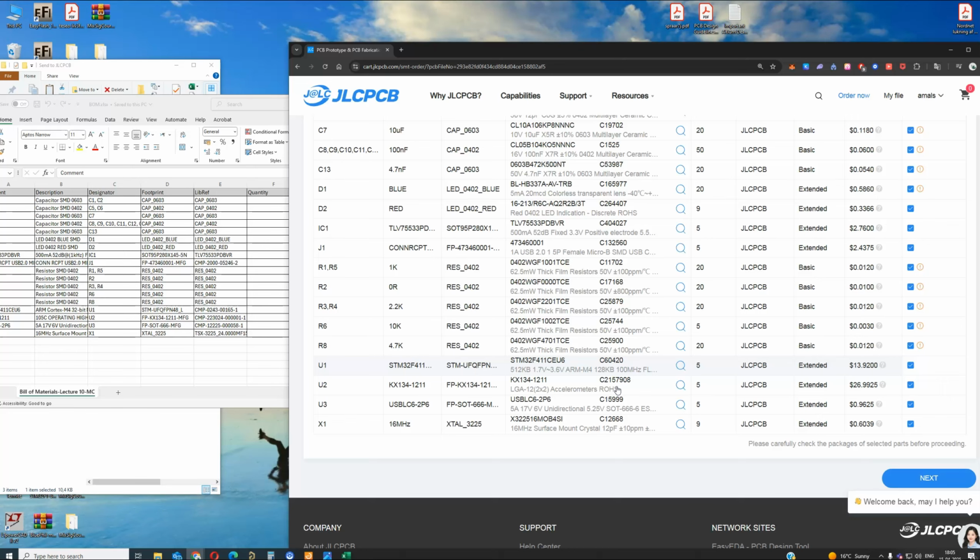So you can see here, this indicator is for the cathode. So this is wrong as well. So we do this. And then for this ESD, they put the pin 1 here, which is here. So we correct it. And for the LDO as well, we have the indicator here for the pin 1. So this is also wrong.